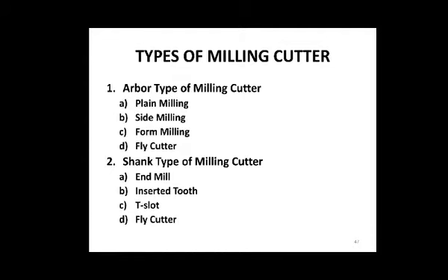When machining a tough material such as stainless steel, however, shallow flutes and a square cutting edge will optimize material removal and tool life. A wide variety of materials are used to produce the cutting tools. Carbide inserts are the most common because they are good for high production milling. High speed steel is commonly used when a special tool shape is needed, not usually for high production processes.